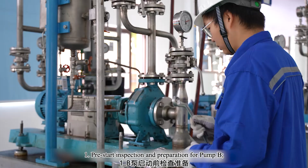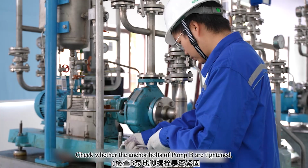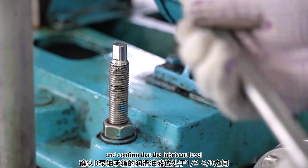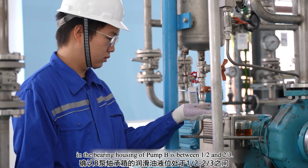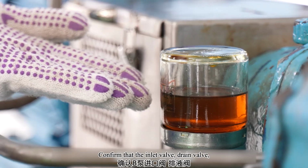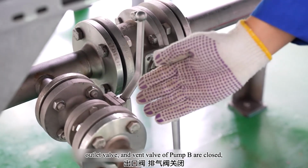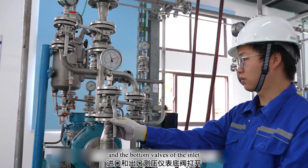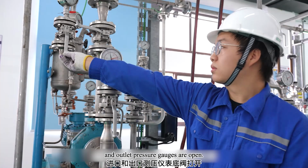First, pre-start inspection and preparation for pump B. Check whether the anchor bolts of pump B are tightened, and confirm that the lubricant level in the bearing housing of pump B is between 1/2 and 2/3. Confirm that the inlet valve, drain valve, outlet valve, and vent valve of pump B are closed, and the bottom valves of the inlet and outlet pressure gauges are open.